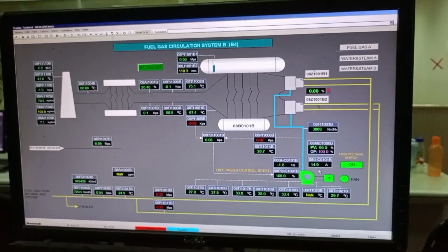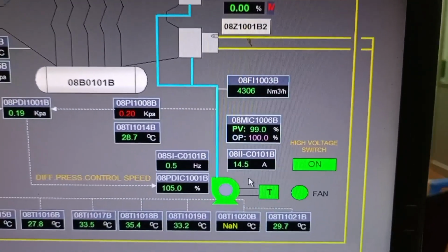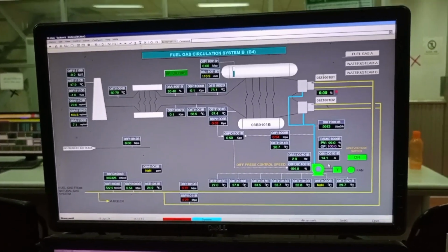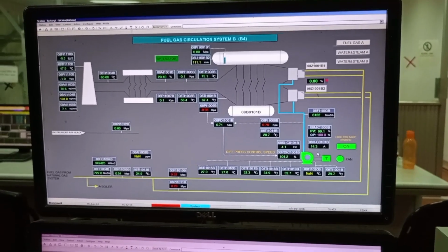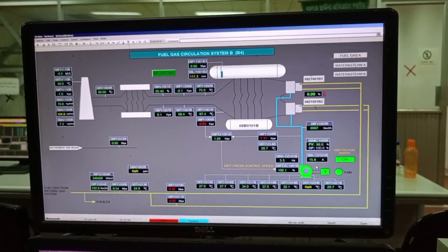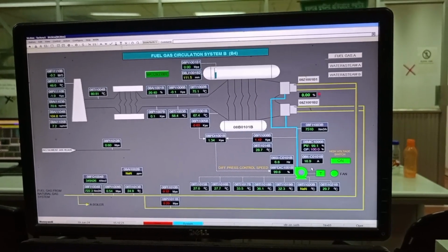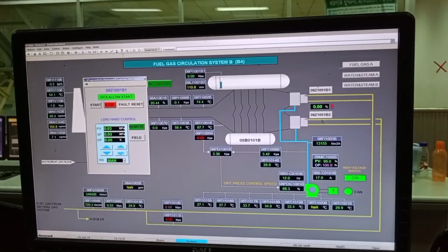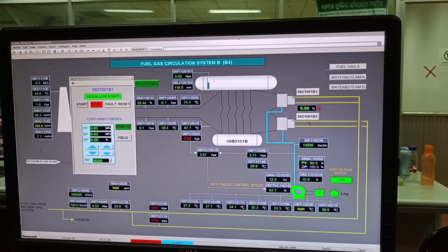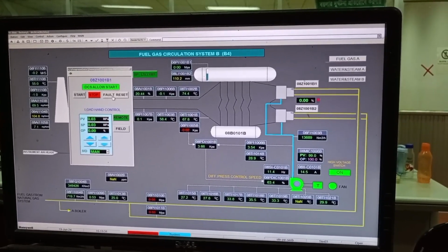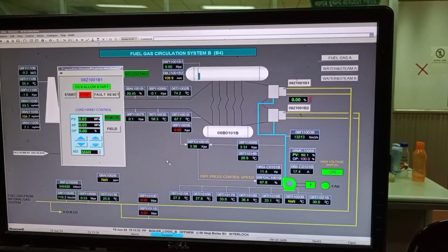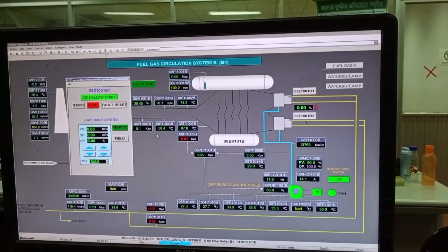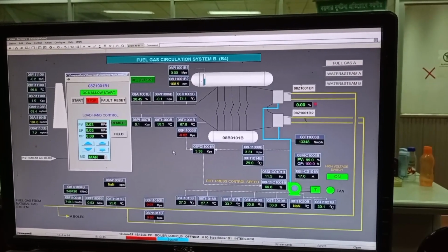When we need maximum steam, then we need to flow sufficient water, and the drum level should be maximum or a steady level, because for maximum steam flow sufficient firing is needed, that means gas flow and water flow, and at the same time within a short period maximum steam will be generated, and so this level will decrease, maybe shortly.